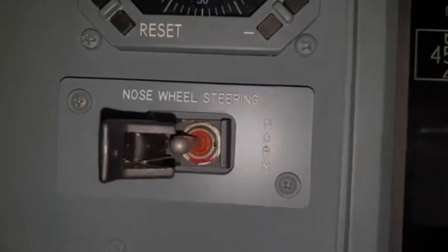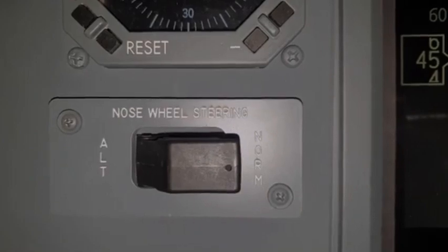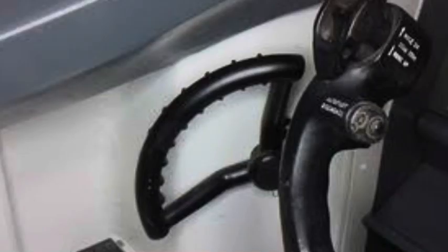Normally the aircraft is steered on the ground by a steering wheel which is attached on the left side, and only the captain can steer the aircraft because we do not have a steering wheel available for the first officer. By using the steering wheel, the captain can steer the aircraft to a maximum of 78 degrees on the ground, but mostly during straightforward taxi routes, we can steer the aircraft by use of the rudder pedals as well, but that steering is limited to 7 degrees. More than 7 degrees we cannot steer.